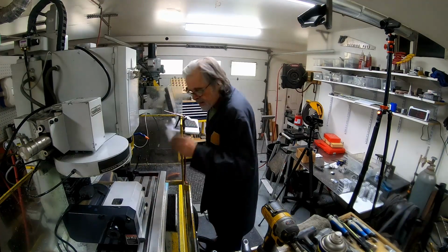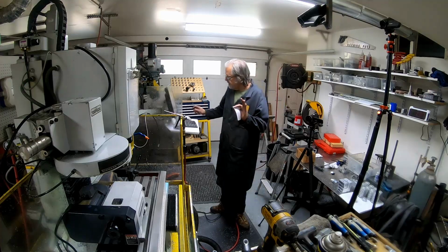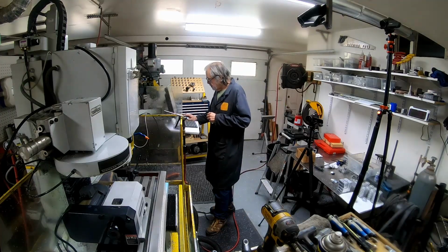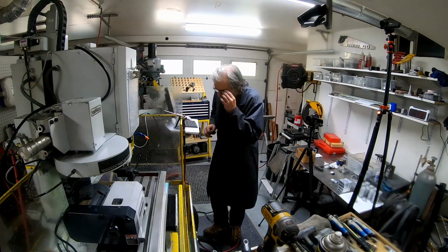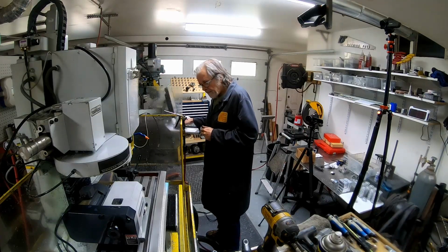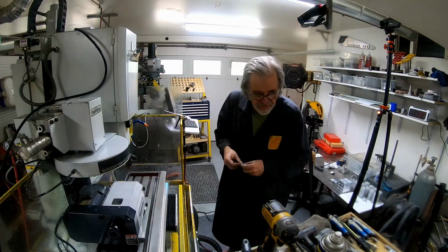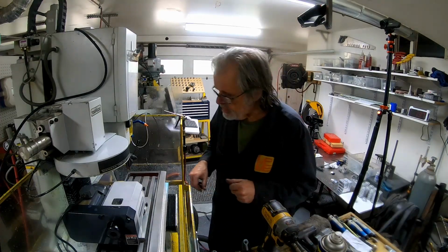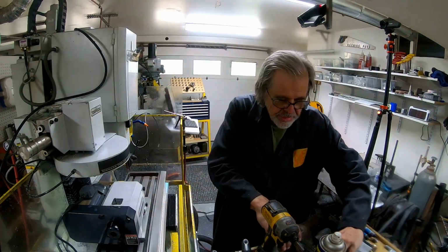Okay, so the paper is barely dragging, and paper is 3/1000 thick, so Z, excuse me, Z is now 0. Gotta remember which direction is which, and of course, since I changed things, I need to revisit X.